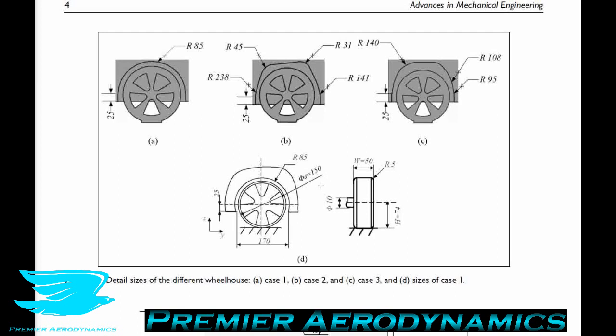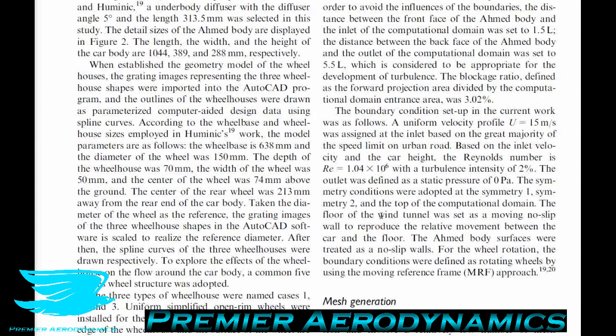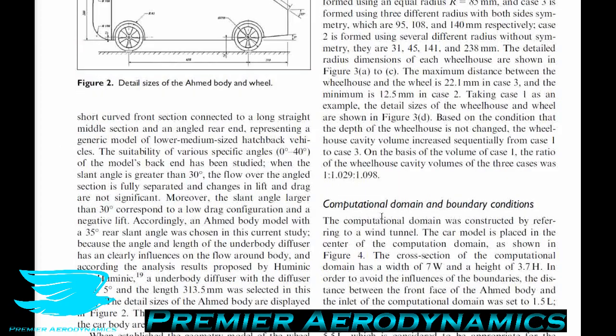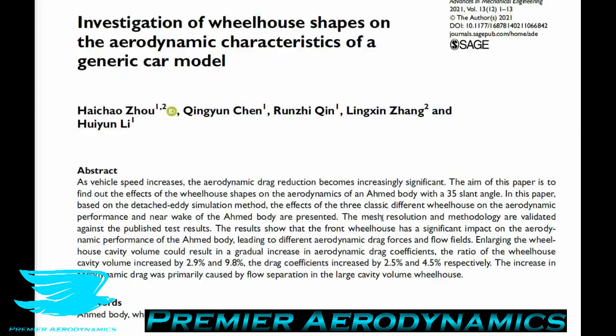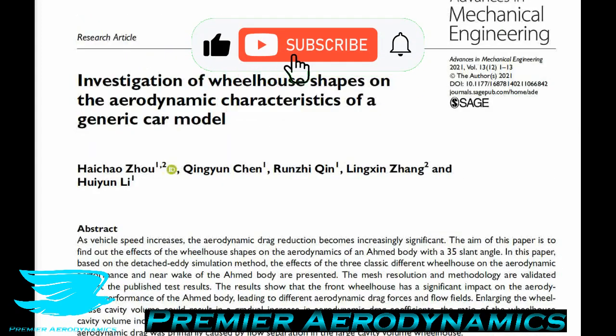We're really going to be focusing more on the flow physics in this podcast because I think we can trust that a lot more. To get the flow physics right, you don't need as accurate a CFD as if you want to get the force coefficients right, because there might be some small differences in the flow physics, but it's not really that discernible to the naked eye, so we can trust the flow physics better.